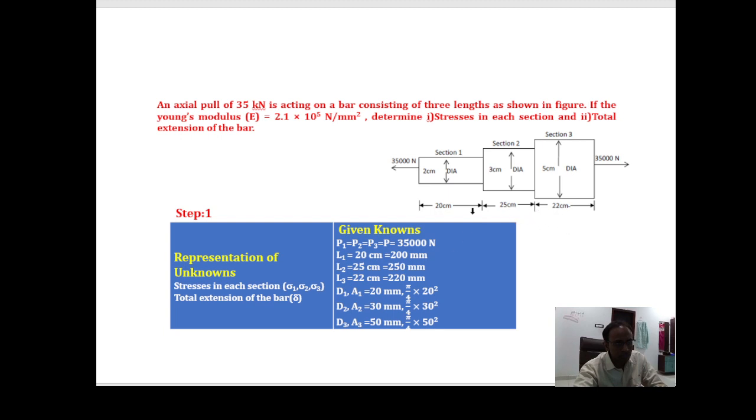It is important to make all of them consistent in general for all these problems, because stress is generally expressed in Newton per mm square. We can convert any force units to newtons, and any length units or distance measurements we generally represent in mm. Similarly for the area units. So if you convert them and keep them ready, we can simply use the formula.